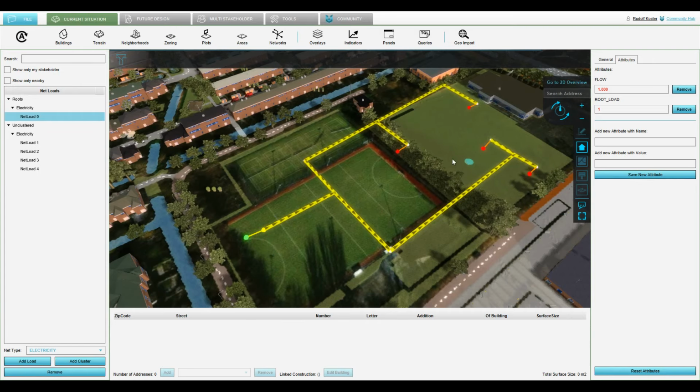If the entire network is structured as a tree, you won't see much difference depending on where you place the root load. However, there are some structures possible where there are cycles in a network, lines which connect back to other lines. And in those cases, placing the root load in a different location will mean that the flow through the network occurs in a different way.